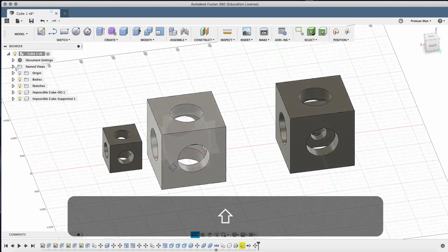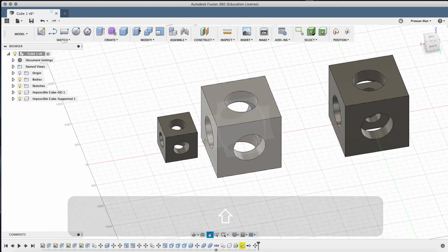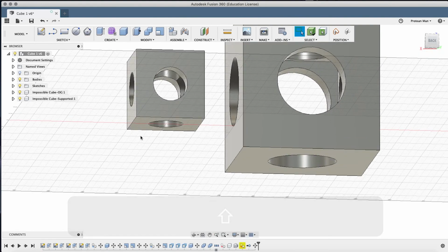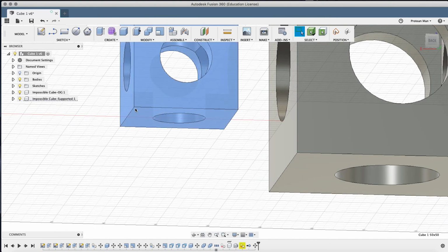You can go any other direction you want, X or Y. Z will not work the same way. So now I need to create supports where this bottom layer has some kind of fill from the ground up until it hits this, so the printer can actually print this bottom layer. Otherwise it's printing in midair and it just makes a mess. So let's make our own supports.